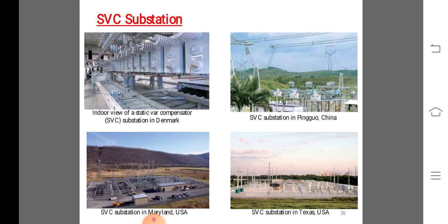The capacitor bank is normally subdivided and connected to the substation bus bar via one circuit breaker per sub bank. The regulator generates firing pulses for the thyristor network in such a way that the reactive power required to meet the control objective at the primary side of the compensator is obtained.